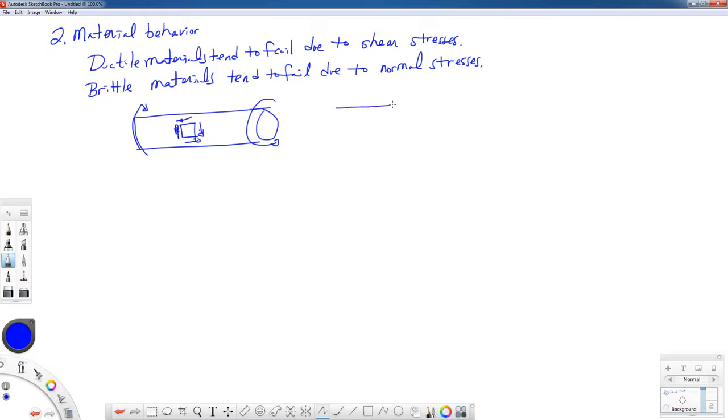There's probably some good pictures you can find on the internet of this, and I also have a video associated with the Mechanics of Materials lab. The distribution doesn't quite look like that, but it's a radial distribution. I'm trying to show here that this surface will go clean straight up and down. There's a video associated with the lab AEM251 that I'm responsible for, and you can see the failure surface of a ductile steel bar in there. So as these two pieces twist, the maximum shearing stress goes here. So this would be a shear failure.